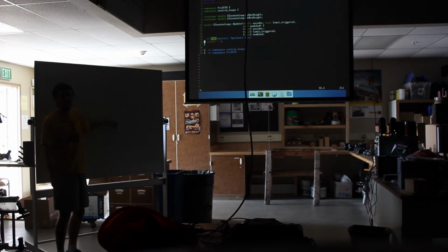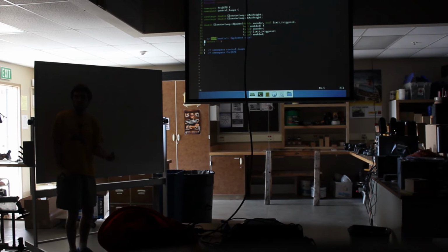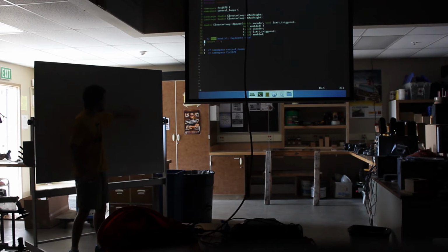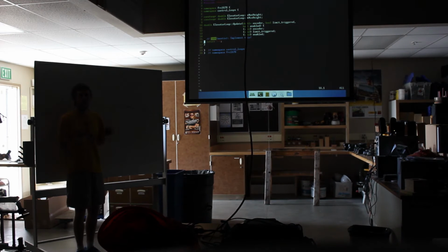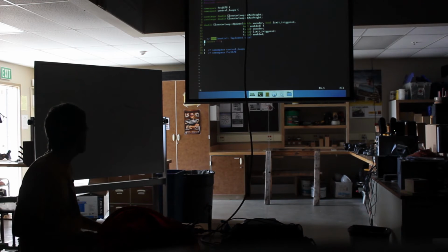So the driver will say, hey, I want to go up here. And then this box says, okay, I'm zeroed, I'm going to give that to you. Or I'm not zeroed, let me first home, and then I'll give you your goal. And then it can command a goal to the PID loop. So the PID loop can then move down in a slow, controlled manner to 0. And then once we found it, we could implement motion profiling or something, or we could just jump to the goal. So we should start writing out some of those pieces.